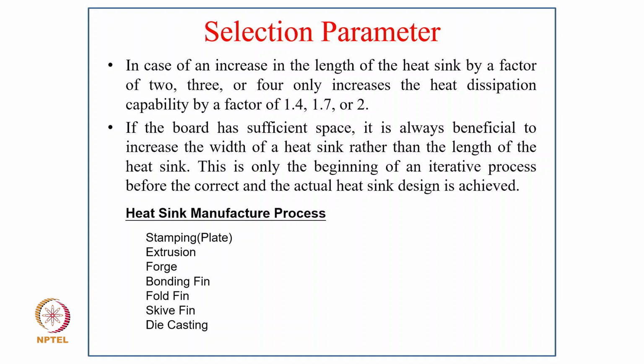So if the board has sufficient space, it is always beneficial to increase the width of the heat sink rather than the length. And this is only the beginning of the iterative process before the correct and actual heat sink design is achieved. Coming to the heat sink manufacturing processes, they are stamping as a plate, then extrusion,